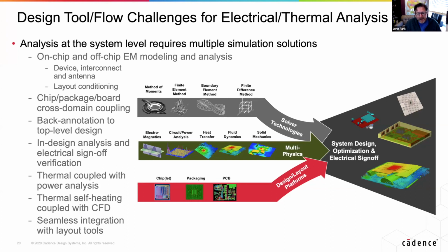So you have to model the power, the VRM from the board through the package or the interposer up to the chip if you really want to know what's happening power delivery wise of that. So it's, again, a system level problem as you move into this world of multiple chiplets.